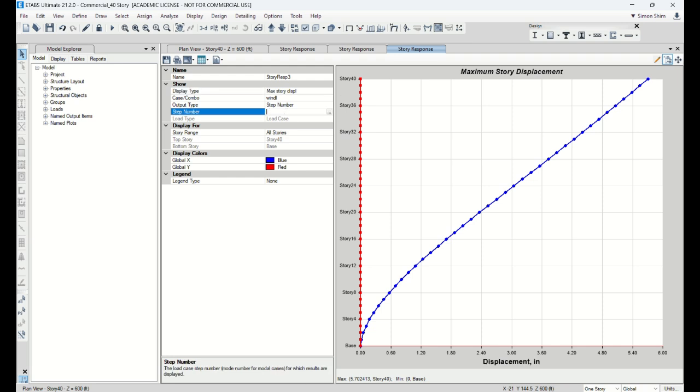So here I'm showing the second wind loading, wind load 2. Wind is blowing in the Y direction. Let's guess what, how much? I have 35 inches deflection here, right? In the X direction ETABS calculated 5.7 inches. Now in the Y direction I have 35 inches. Just assume the total building height is 600 feet divided by, let's say, criteria 500. I may end up limiting my maximum deflection to 1.5 feet or 16 inches, something like that.